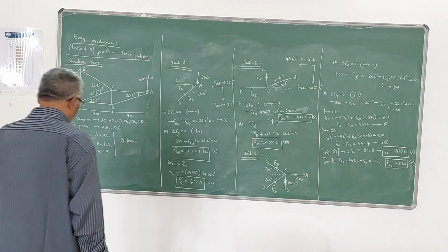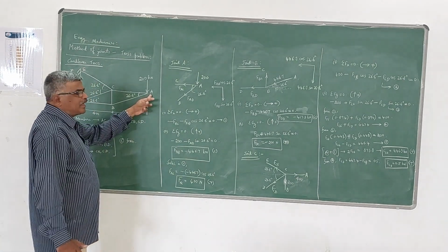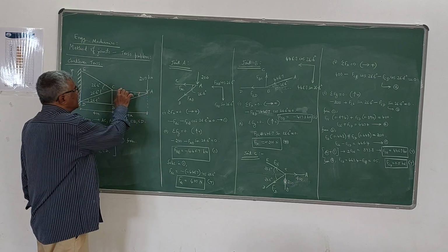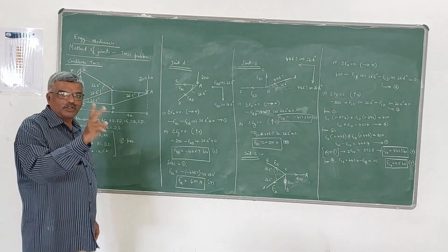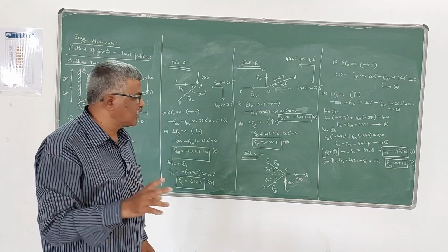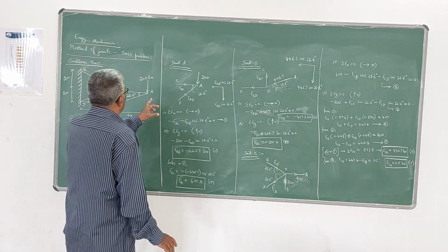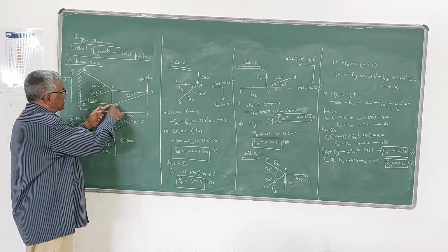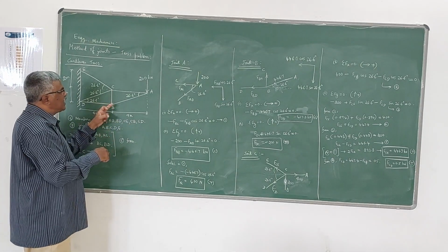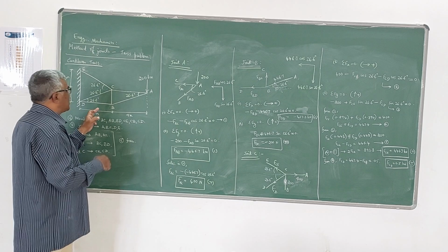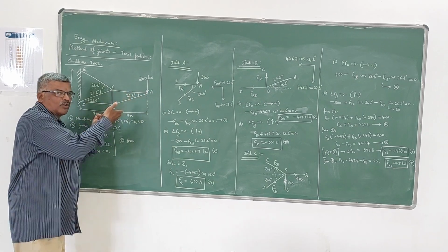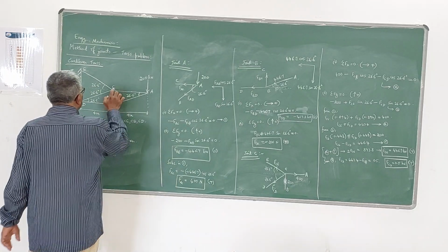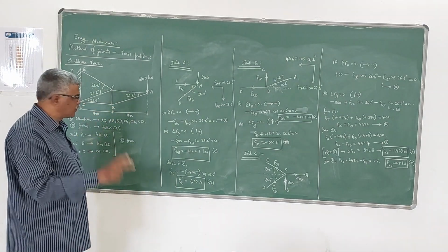So here, if I take joint A, I can easily find out the forces in the members AB and AC which are meeting at joint A. Only 2 unknown forces are there. So first joint I can take A, then we can move towards B. When you move towards B, there are 3 members connecting at B, AB, BC and BD, out of which AB force is already known. So therefore unknown forces in BC and BD can be found out, 2 forces.